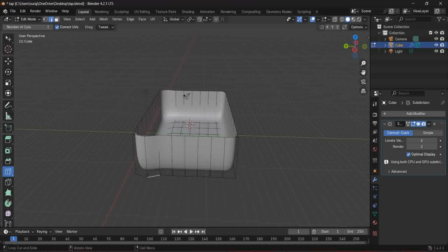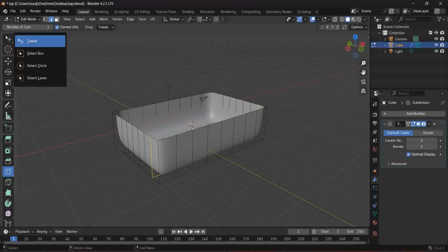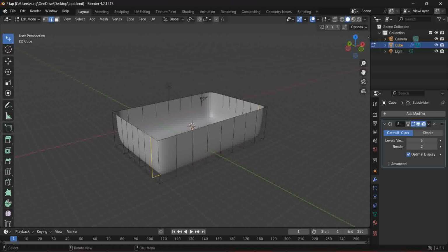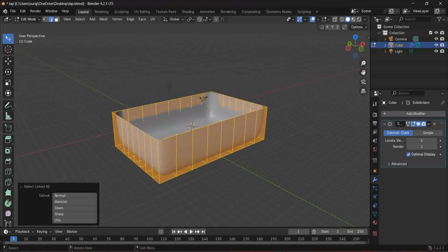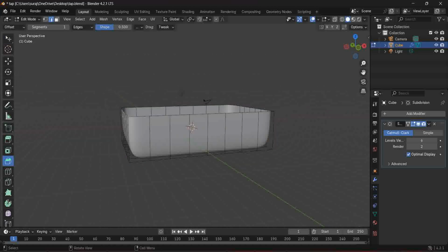Just a second, instead of doing this, select control, escape this and go to Edit mode. Now as you're in this, you have to press control to select all the objects. After you do so, I want to select this bottom edge. So I'll press alt and click on this edge. You can see the whole thing has been selected.